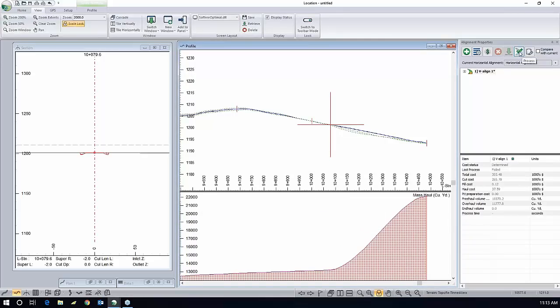And then just press process. And then after a few seconds, you should see definitely a lower cost road than $303,000. And it should be balanced. You should see very little red. Right now you see waste happening throughout the length of the road. So this red means waste. Just have to go through a little bit more and then find the optimal here.